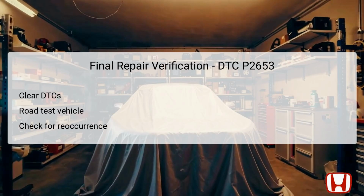Once repairs or replacements have been completed, the final verification process begins. Clear any diagnostic trouble codes from the PCM using the HDS diagnostic tool to reset the system's memory. Follow this by conducting a road test of the vehicle to monitor its performance under actual driving conditions.